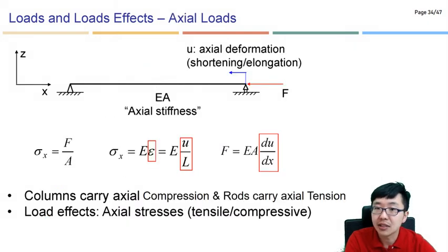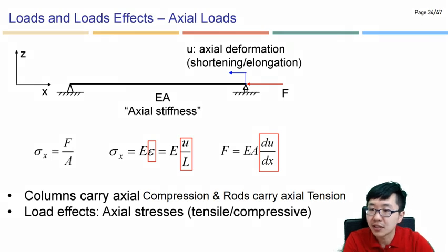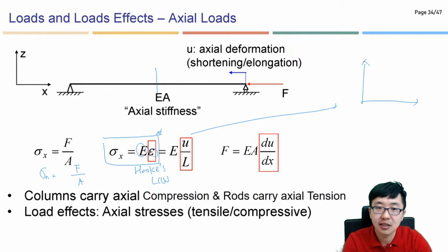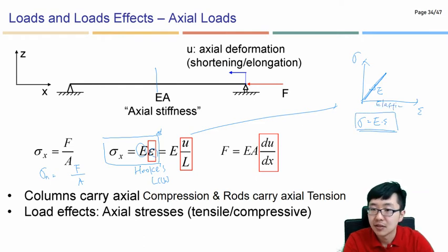So here we can discuss the actual loading conditions. In this case, this is the normal stress, that is the applied force over sectional area, and we've learned this like Hooke's law. So sigma equals E epsilon, or you can plot it like stress versus epsilon, and this is E epsilon. So this is the elastic region, so that we can derive all those details.